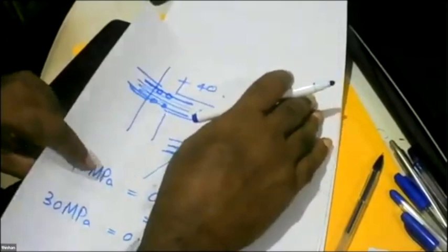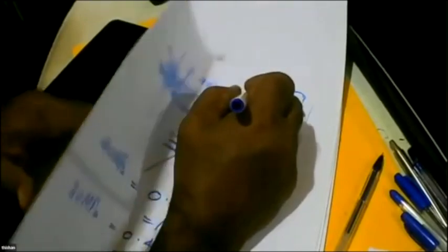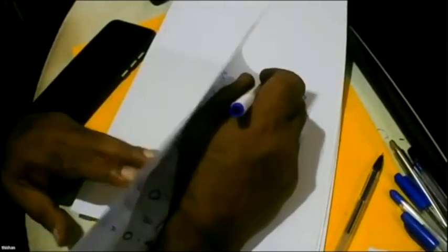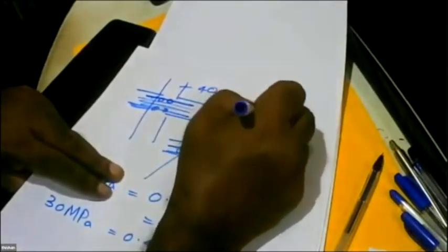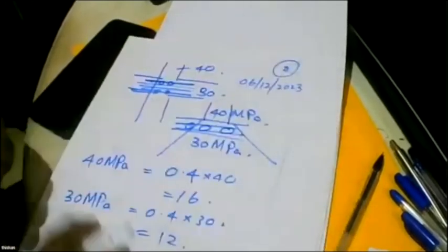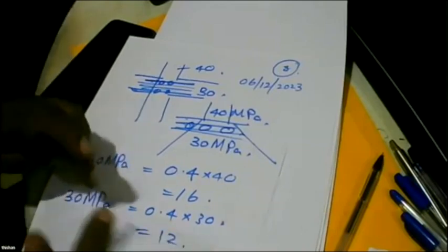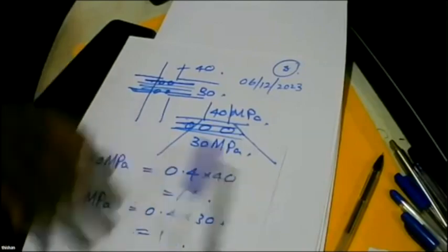No. Up to 25% fly ash, you are free to do anything, provided the fly ash is type F and the carbon impurities are low. So you have to get fly ash which has passed the tests. If you ask a cement manufacturer, they buy only the fly ash that passes the carbon test. If there's too much carbon, then it's an impurity. So you have to get the specification for class F fly ash and check whether the product that you buy satisfies that. But the moment many construction companies are buying fly ash, it will become readily available, high quality fly ash.